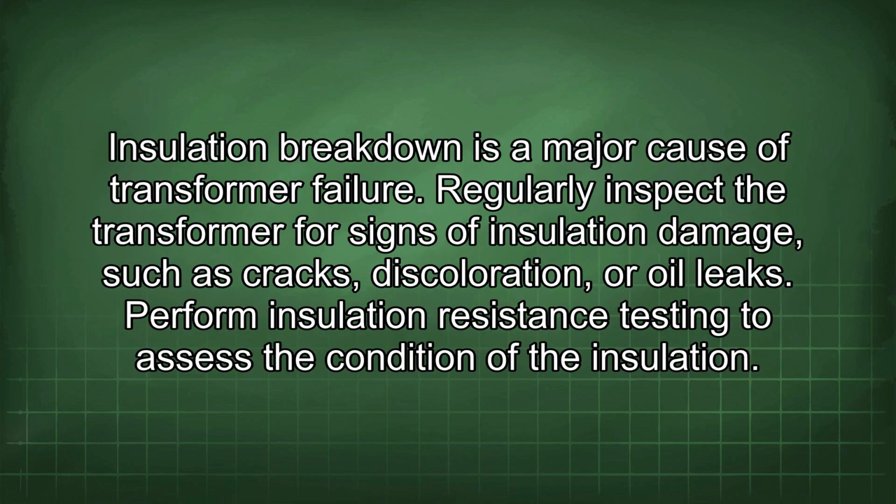Insulation breakdown is a major cause of transformer failure. Regularly inspect the transformer for signs of insulation damage such as cracks, discoloration, or oil leaks. Perform insulation resistance testing to assess the condition of the insulation.